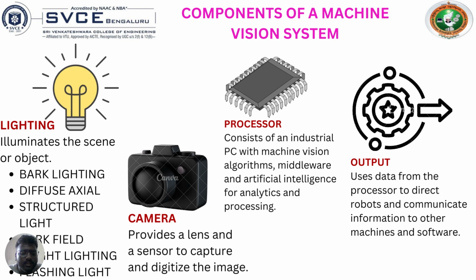For diffuse axial illumination, the light comes from the left, and via the optical route the diffuse illumination light is reflected downwards on the section. A semi-transparent mirror reflects the light via the partially transparent mirror to the component, which reflects the light back to the camera, producing a very uniformly lit and homogeneous-looking image.